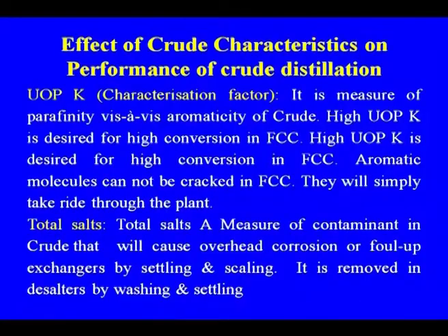Characterization factor, we already discussed, is a measure of the paraffinity of the crude. High UOPK is desired for high conversion in the FCC, and aromatic molecules cannot be cracked in FCC. So, depending upon the characterization factor, you can have an idea of the products you are getting from the separation.